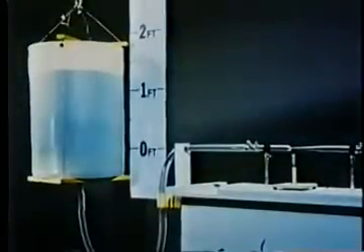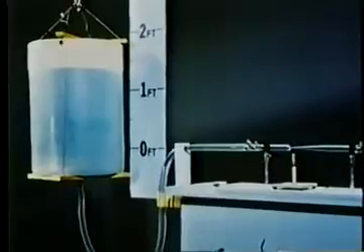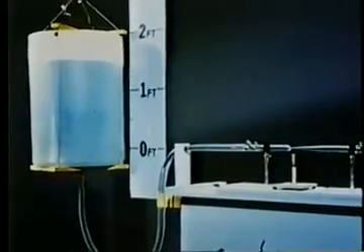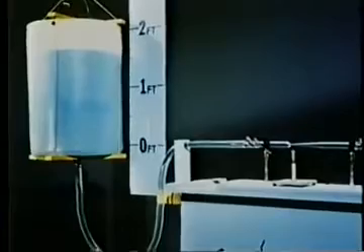Now, even a stable nucleus can decrease in size and eventually disappear because its gas content may diffuse into the surrounding fluid. We can show this with the Venturi experiment by comparing the cavitation inception pressure for freshly drawn water with that for water which has rested undisturbed for some time. Because the discharge is to the atmosphere, increasing the driving head increases the velocity and thereby reduces the static pressure at the throat.